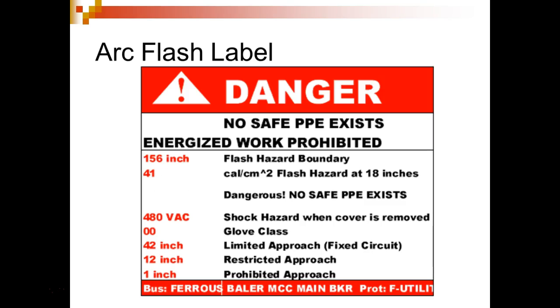Danger. No safe PPE exists. Energized work prohibited. So if you ever see this one, it means you shouldn't even get into this if you had your PPE on. No safe PPE exists. Energized work prohibited. So if you see this, you're not ever supposed to do work on this thing live.